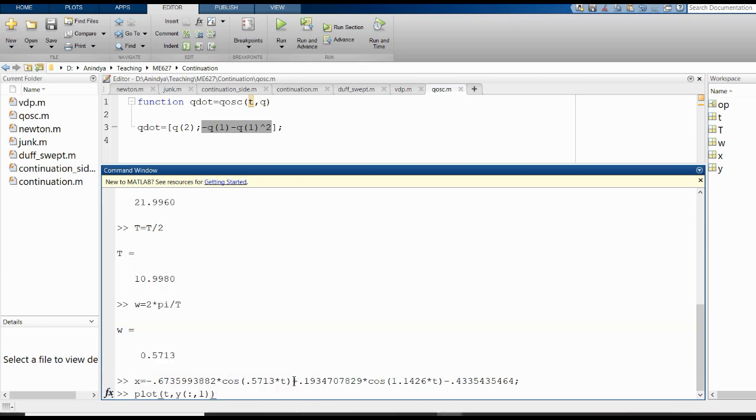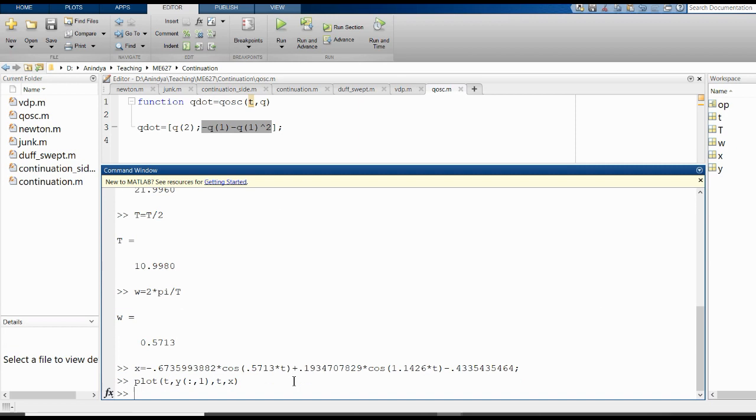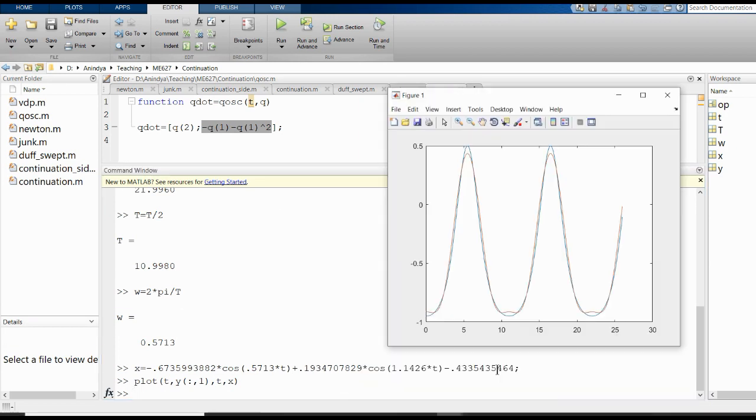And then what I will do is I will plot these two, and if you look, you see that the match is not bad, right? So the time period is reasonably matching. You can see here this peak is not fully captured. Over here there is a bit of distortion. So it's not really working very well, but it is working. Okay, it is giving you an answer for something that is not very far from the singular point. It's not an unreasonable answer. So this is harmonic balance.